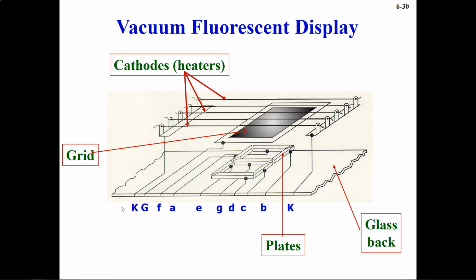Now, there are two ways to stop the conduction in the triode tube. First, you can make the grid slightly negative, and that will repel the electrons. If it is negative, then it will repel the electrons, and they will not pass through the grid to the plate. And the second solution would be to leave the grid positive, and drop the plate voltage to 0 volts. The plate will not attract any electrons, and the triode tube does not conduct electricity from the cathode. So these are the two ways we can stop the conduction in the triode tube.